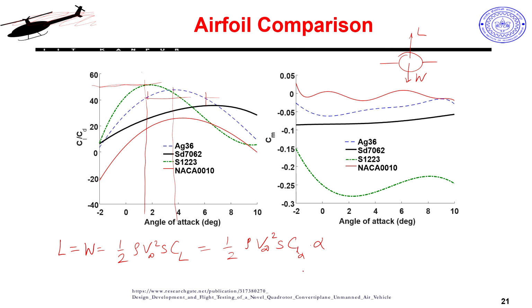Okay. So, now from this I can see my angle of attack required to fly, or I can keep it like this, alpha V infinity square equals twice W by rho S CL alpha, right, which means for this value to be obtained, if I increase this, I will have to decrease this, right, which means if I want to reach my destination quickly, I would like to fly at a relatively higher speed, the best speed I can fly at without compromising my L by D too much.